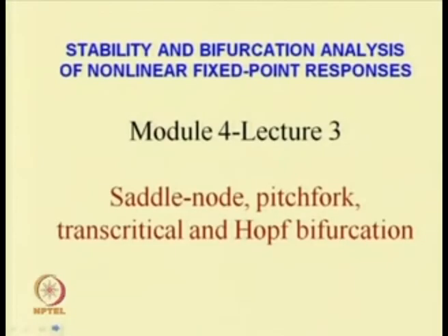So, last class we discussed static and dynamic bifurcations, and there we studied the stability and bifurcation analysis of nonlinear fixed point responses. Today we will have more discussion on the saddle node, pitchfork and transcritical bifurcations, and also on Hopf bifurcation, which is a dynamic bifurcation. So, the static bifurcations are saddle node, pitchfork and transcritical, and the dynamic bifurcation is Hopf bifurcation.